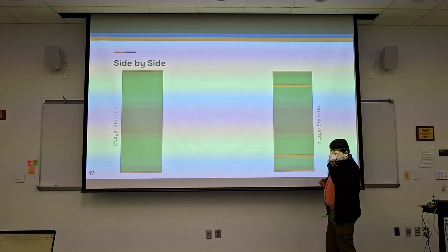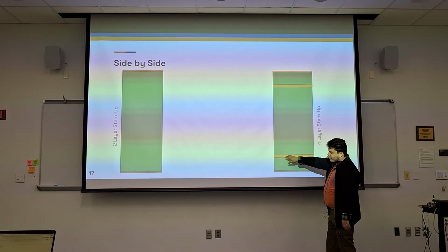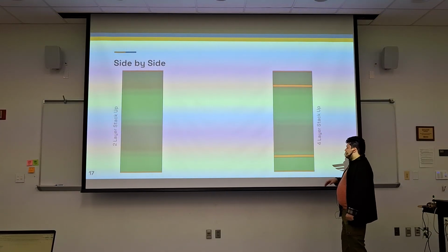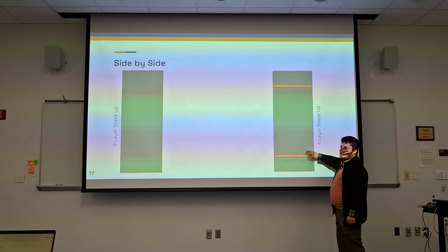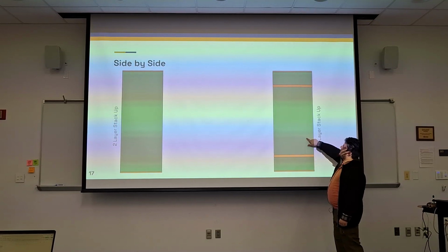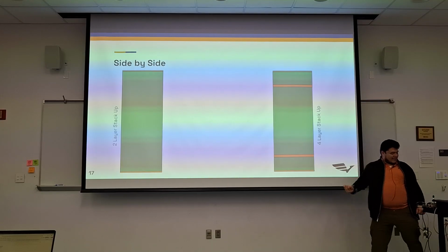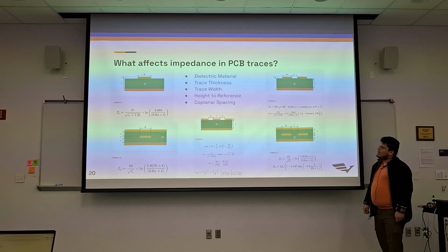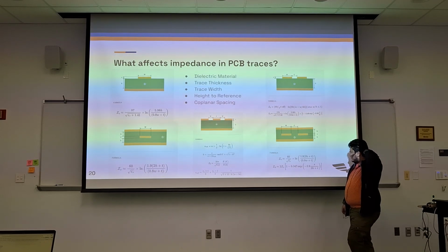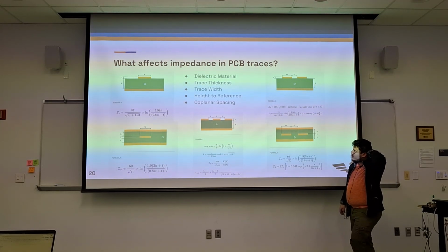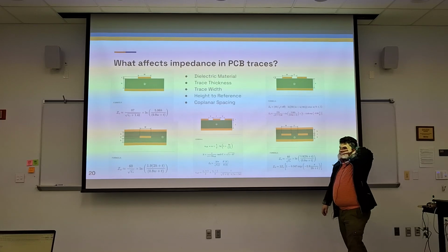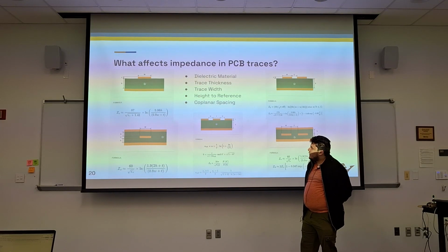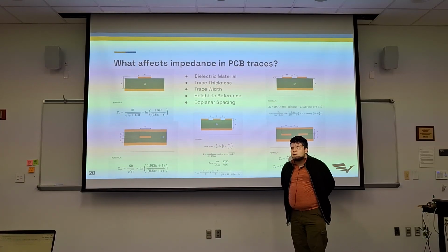So if you do end up doing an asymmetrical stripline, because you want to really maximize that signal integrity for those diff pairs, make sure it's the asymmetrical one, because a 4-layer board is not symmetrical. But that does exist. Generally speaking, I just don't think we're using anything high frequency enough where it's necessary. It'd be a cool challenge, but not necessary. So, something to consider. Maybe on an 8-layer board, like a motherboard.